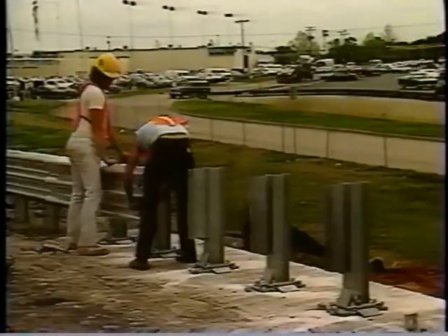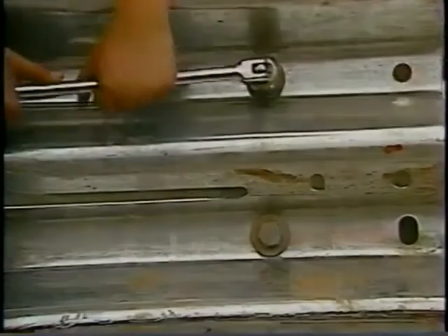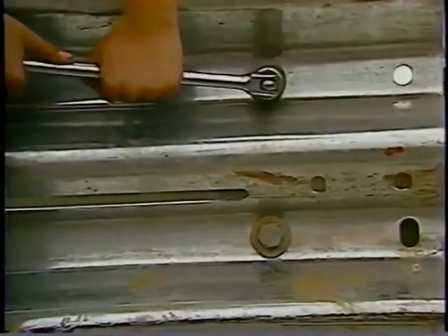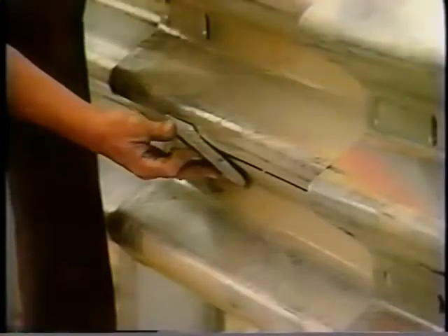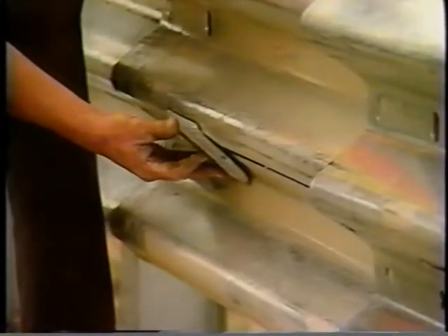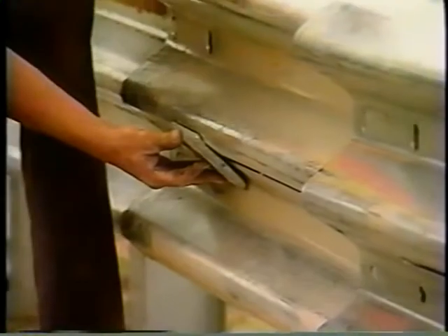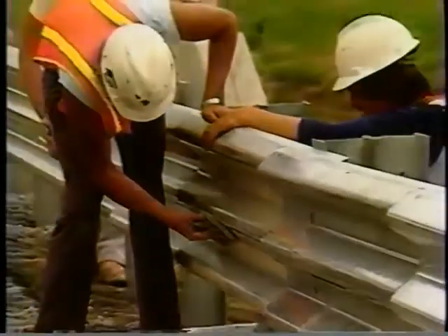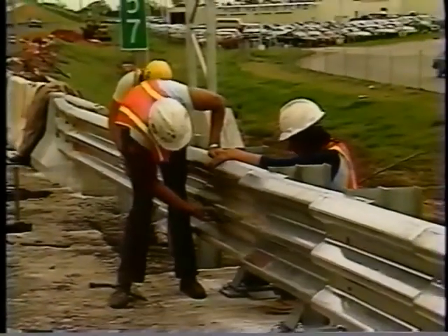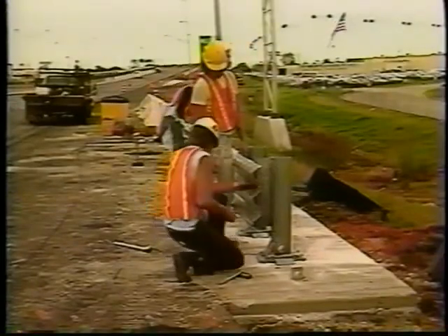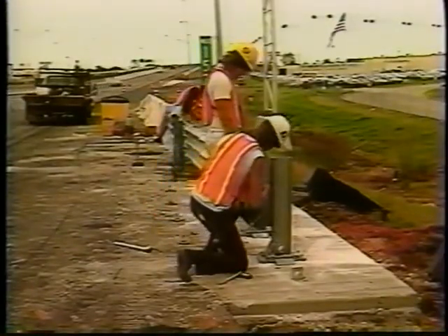Attach the remaining panels, starting with post 4. First, attach the panel to the post with 2 bolts. Then attach this panel to the previous panel using the mushroom bolt assembly. Continue the process for the remaining posts and panels. At post 1, the 3/4 inch bolt assemblies must be left loose.